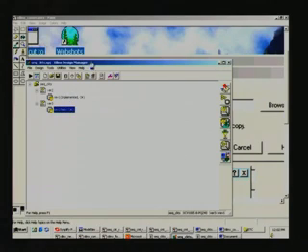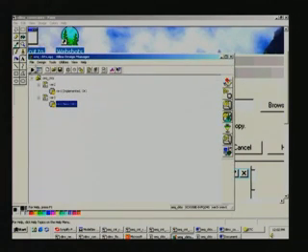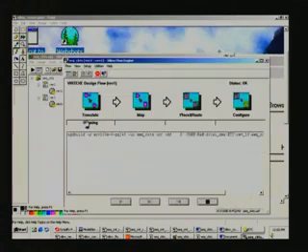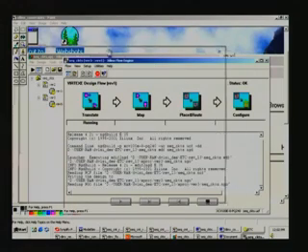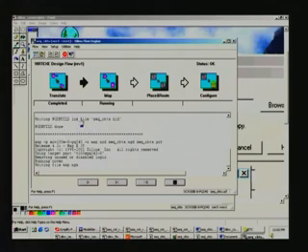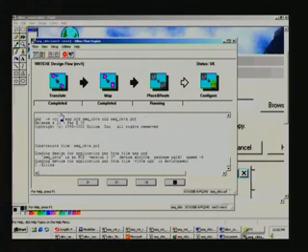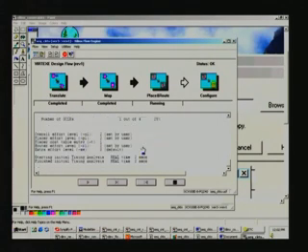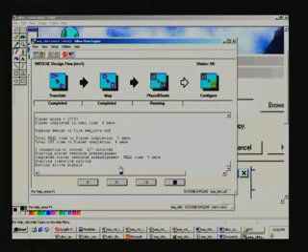Now, what we have to do is start the place and route. The input file for this is the sequential circuits .edf file generated by the synthesis tool. We will click on this in order to start this. You see a new window open up here, and some activity is going on now. You can't read this file anyway, and we will see a zoomed version of the report files later on.